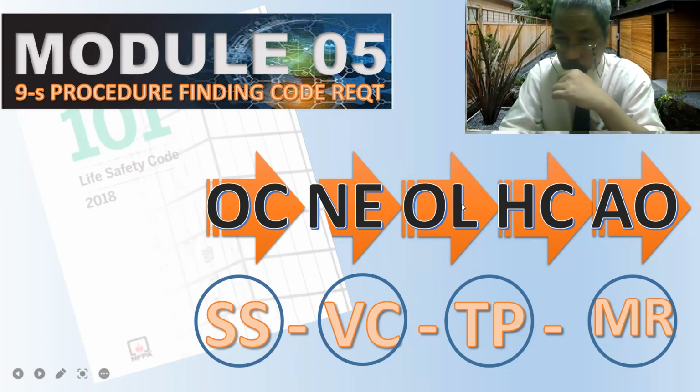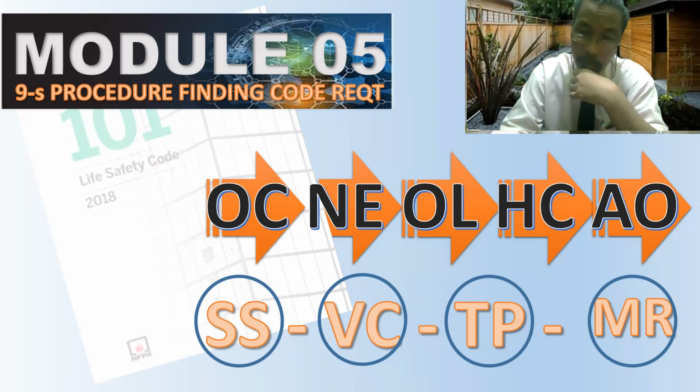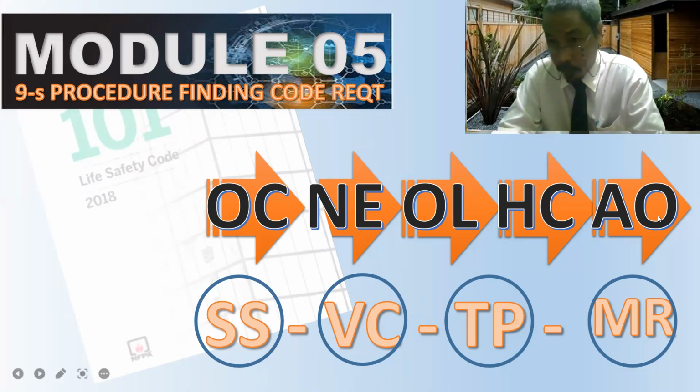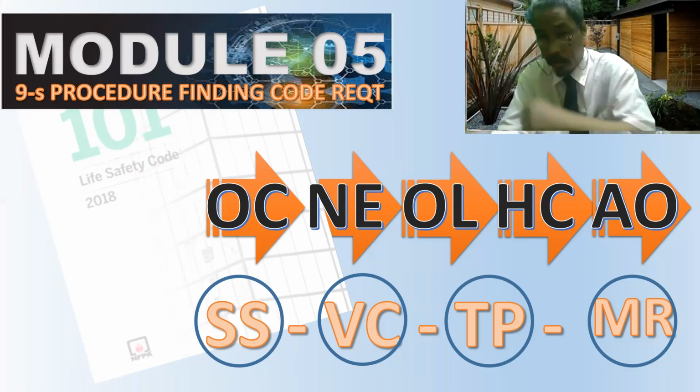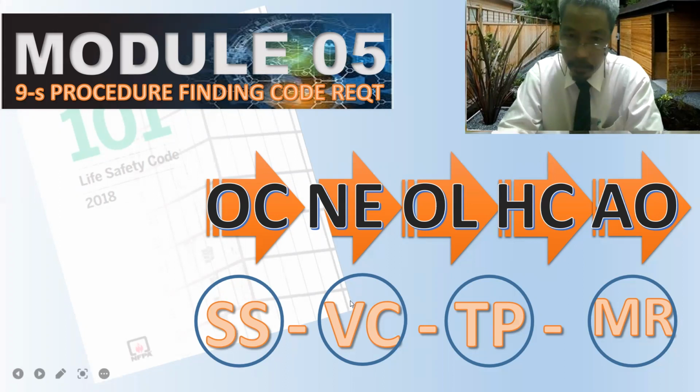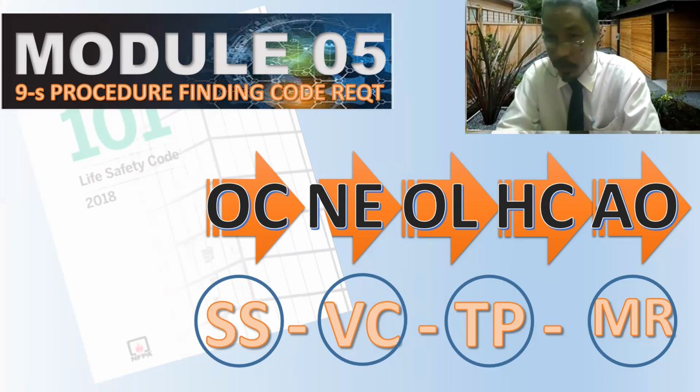Then after computing, we can proceed to the provision of hazard contents. Then we go to the occupancy chapters, and after which we have to look for this special use or sub-classification, and then verify our classification, verify our requirements, and then who takes precedence.